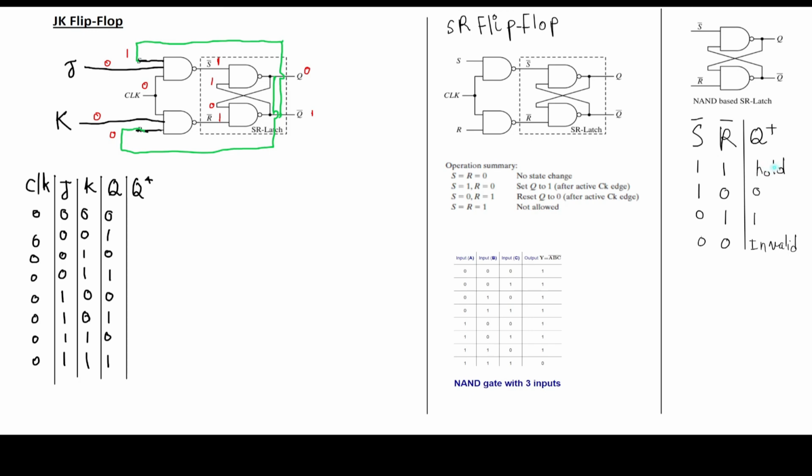the previous state. So if you complete all the combinations the same way as we did here, you're going to notice all of these here, the next state will be hold. It will hold the previous state. So all of these will be the same when the clock is disabled. We can try one more and then you can practice with the rest on your own. So let's try this one just to ensure we're going to get the hold state.